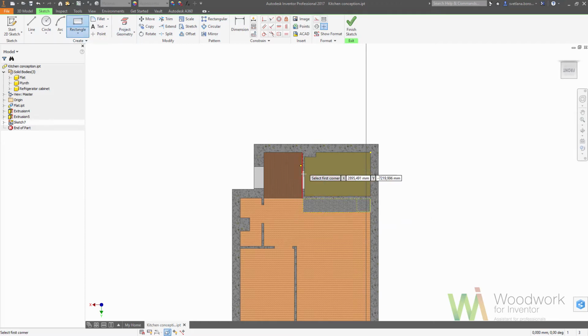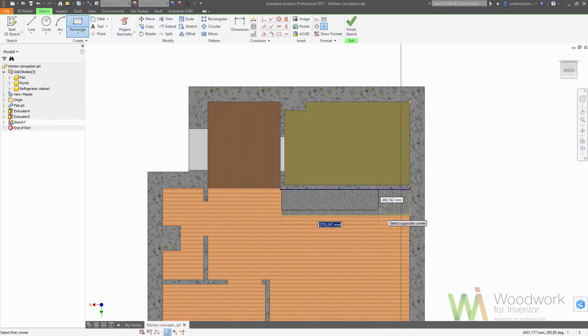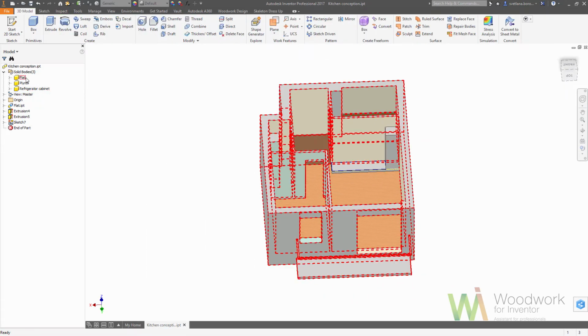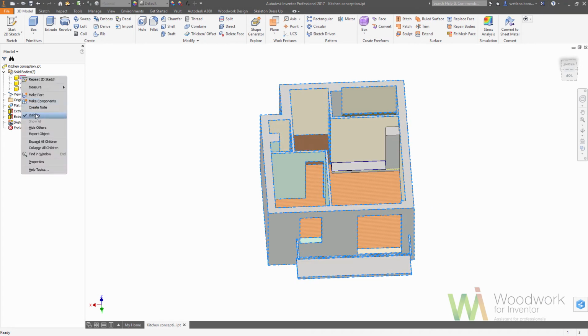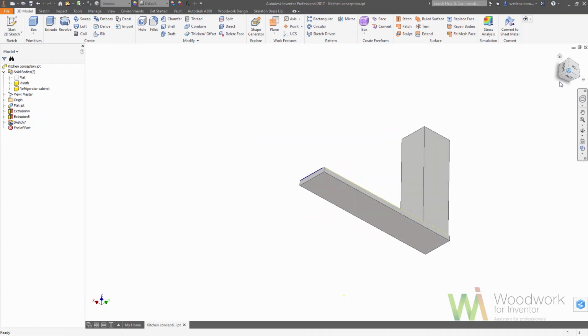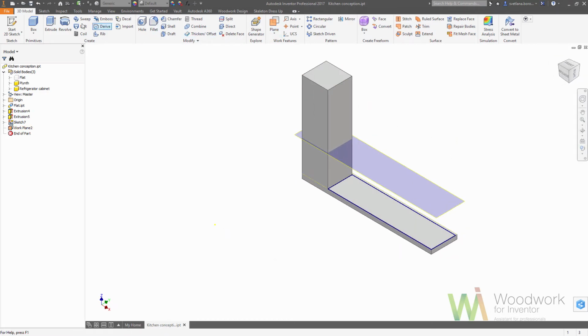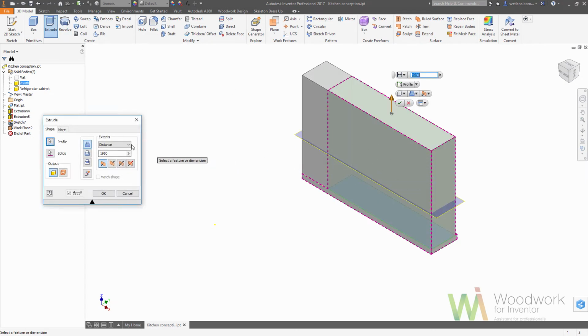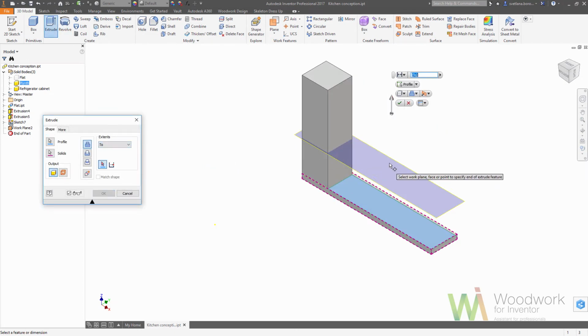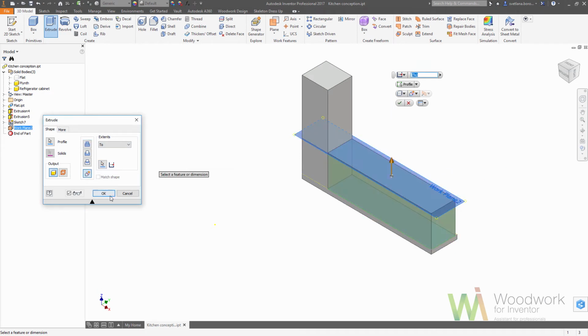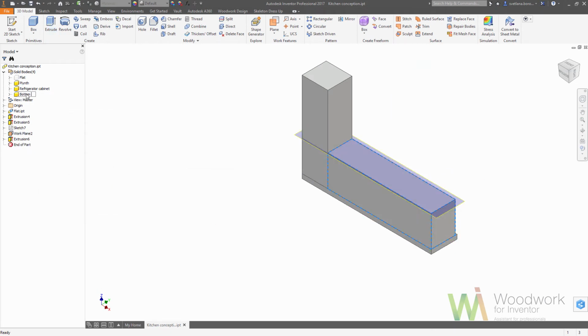Now we can draw another cabinet block. So this cabinet block is the bottom row of the cabinets. So to make our work more convenient, we can hide the flat plan, and now we are defining the height. So it would be equal like the total height minus height of the plinth. Now we are using the To operand to set the height of the extrusion to the work plane. Let's give the name to this block like bottom cabinet concept.